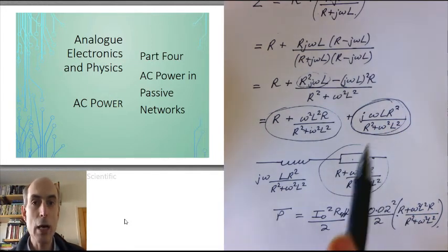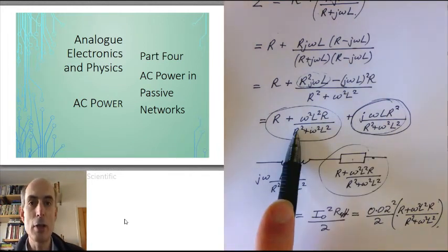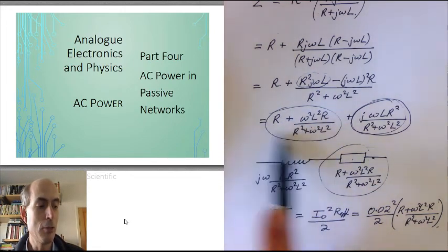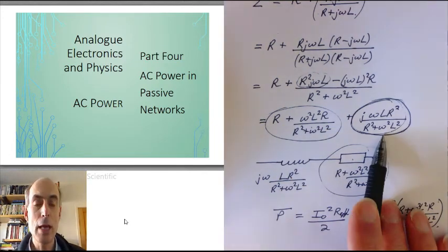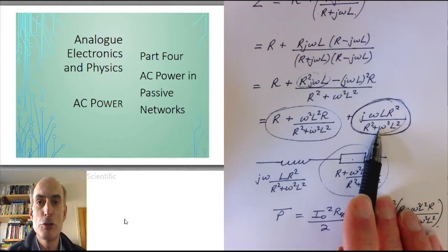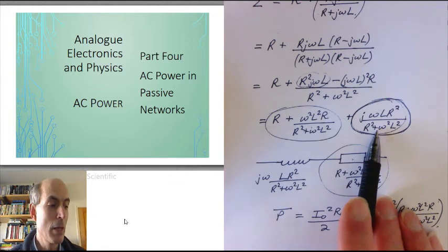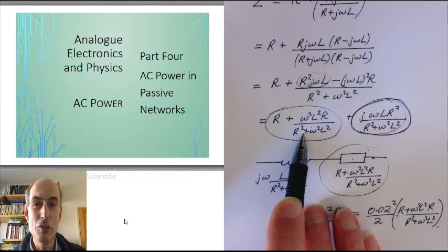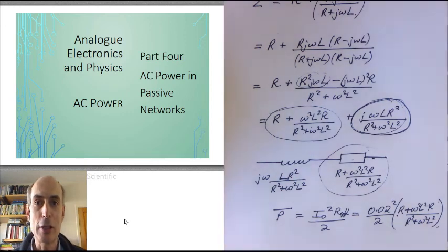When the rate at which the energy is being pushed back into the circuit is greater than the rate at which the energy is being dissipated by the resistive component of the complex impedance, that is the part of the cycle where the total component has a negative power associated with it. The energy being returned from either storage in the electric field or magnetic fields in the capacitor and the inductor is more than enough to allow the energy to be dissipated by the resistive component, and the excess energy is returned to the rest of the circuit.